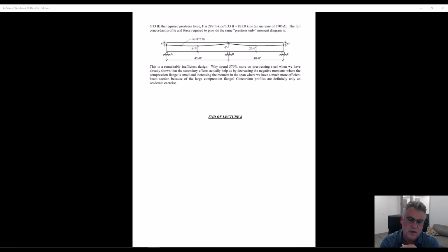Let me summarize. The capacity of a post-tension or pre-stressed concrete beam is very similar to what you came to this class already knowing how to do. You have one more force in there. That's the force in the pre-stressing steel. And the only complication in finding that is determining what the FPS value is. You're going to make sure you use the correct equation: the unbonded equation from this point out. Unbonded for beams. So that part's not at all difficult.